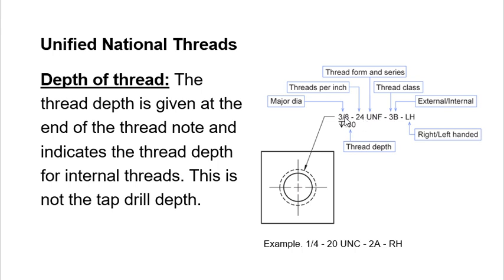Actually, diameter is right here, and that's just a depth symbol there. So the value followed by the depth symbol is the depth of your thread. Concentrate when you study to get these 2 here. Sometimes you forget the thread class. Thread class only has 3. The second one is general use, the standard, normal one.